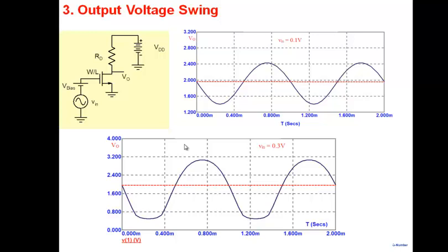Note that the effective voltage across the transistor is decreasing, right? On the negative side, the effective voltage decreases, and as it decreases, my transistor enters into triode region. Why should distortion occur when it enters triode region? Because in triode region, remember, output resistance is very low. And output resistance is low means what? Why is the output resistance low?